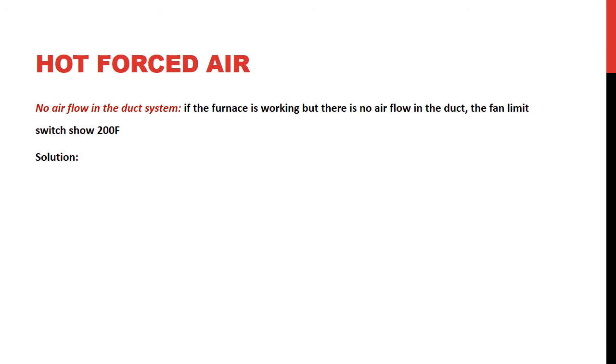Problems of heating systems, and I would like to just highlight some of the problems with forced hot air. Again, if you have forced hot air, probably it's a furnace, or you could have a heat pump. So if there's no flow, one of the most common problems that you will see with forced air is no flow of air. And usually it's going to be a clogged filter. Like 8 out of 10 times it's a clogged filter, or the filter is not working properly.